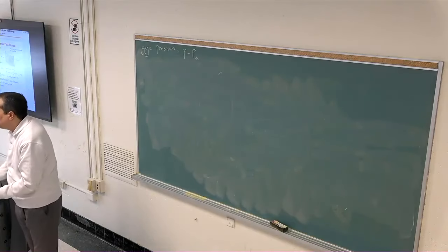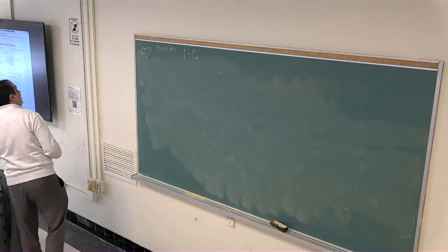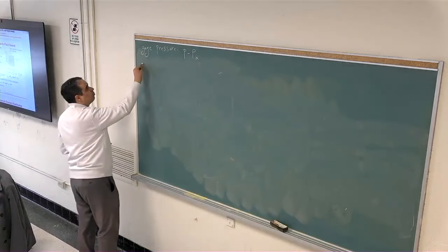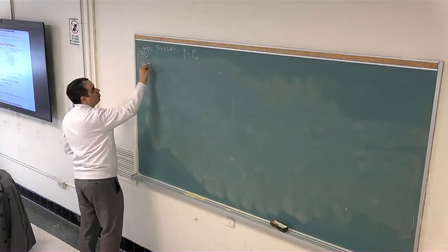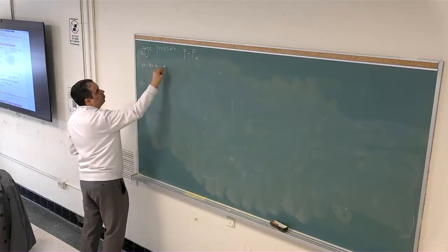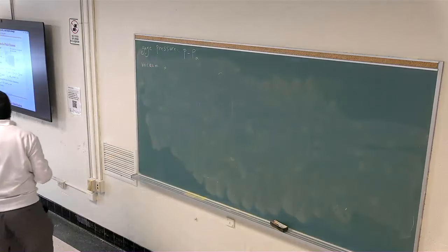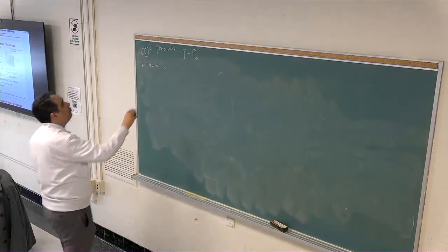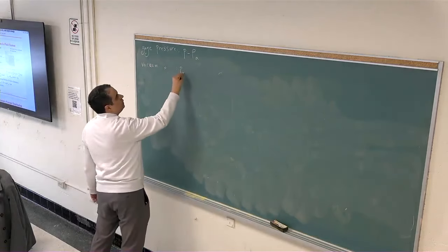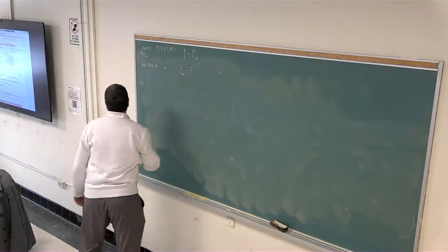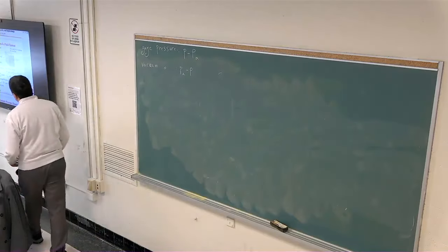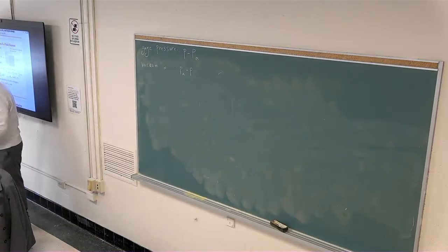It is easier because we omit ambient pressure in our calculation. Vacuum pressure is P ambient minus P. We don't work with vacuum pressure quite often, but with gauge we work a lot.